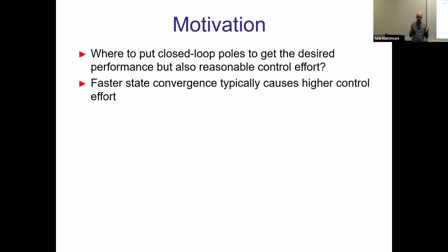So this is the overall idea of optimal controls, where you're trying to find these compromises between reasonable input and reasonable output convergence. This is what is called the regulation problem, where you have zero input and you want to converge to zero from some initial conditions as fast as possible without spending too much energy. So this is the main topic, which is called LQR, linear quadratic regulator. This is an optimal controller, a state space controller. It's still the same state space as we learned before, so it's not some different architecture. It's still that K vector, but for that K vector, you're designing K optimal, which would minimize the energy of the input weighted with the energy of the output somehow. And this is the optimization criteria that we will be talking about, one of them.